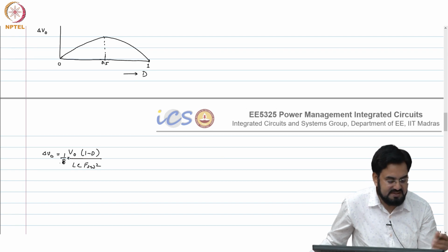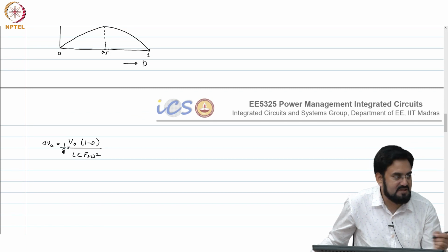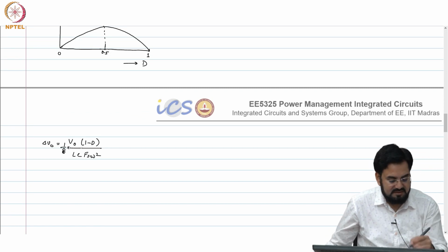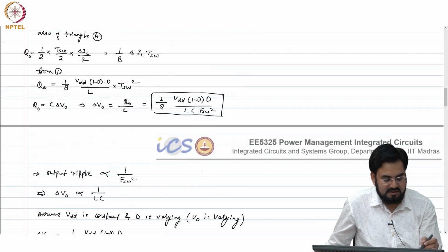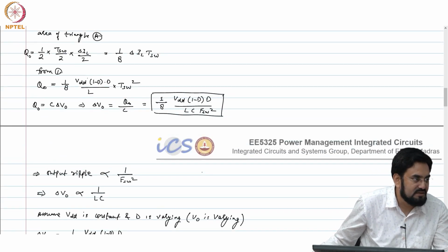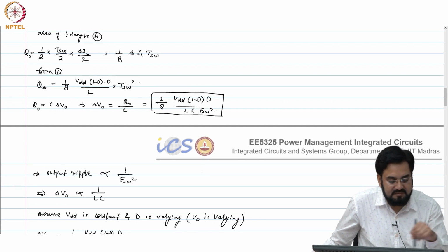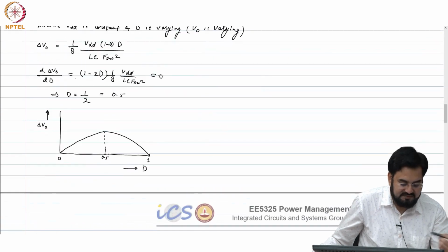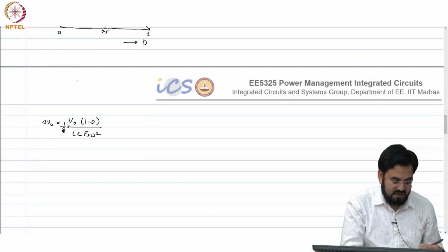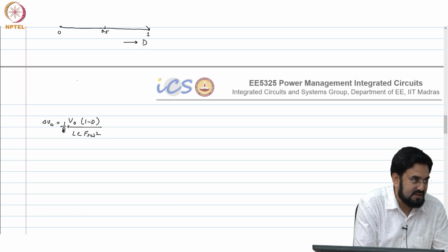So, when you are looking at a maximum peak current, the only difference is the capacitor which comes into the picture, otherwise the duty cycle portion remains the same in both current and voltage, and V out or VDD remains the same in both current and voltage. So, these curves are valid for current as well, if you are assuming that the capacitor is constant, it is not changing.